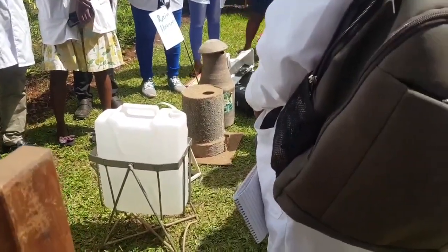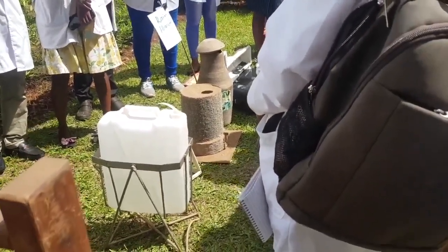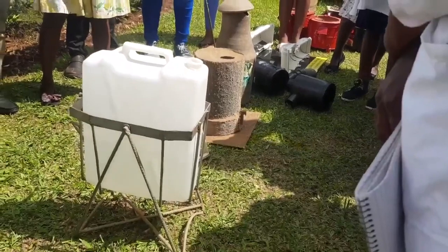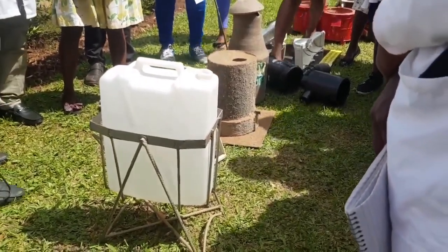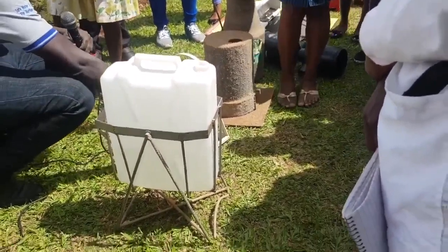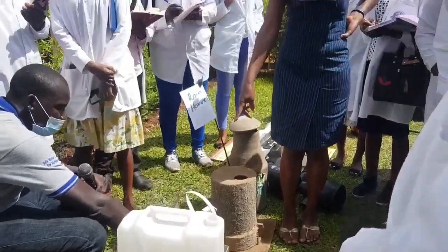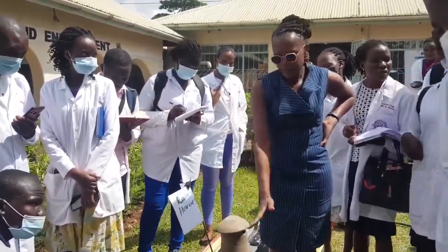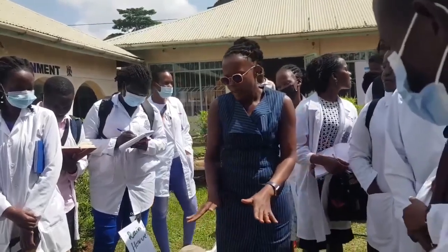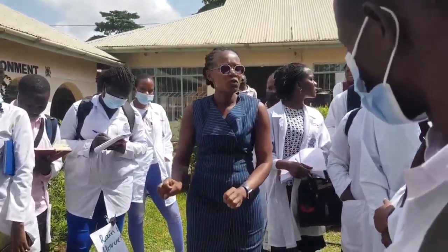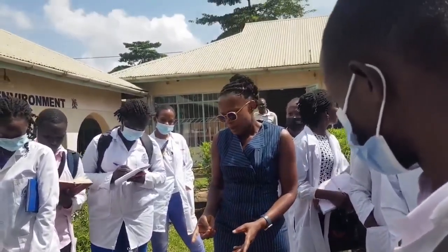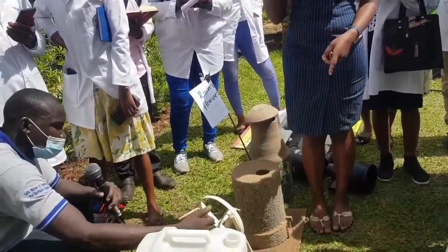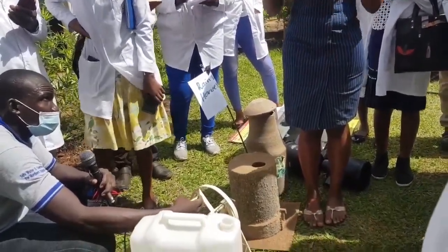You know, when we construct underground tanks, the challenge is getting water from there. So the EMAS tank has its own pump. It's called the EMAS pump. But the other tanks don't have pumps. So we either use electricity to pump water to an elevated tank, or you can do it manually. You can install a rope pump that you can use to pump and get water, the way they do at the borehole. The advantage is that you manage to control the water usage. As you rotate, they are easy to construct and easy to maintain. Though they have a rope that keeps on breaking, so we encourage it to be used at a small scale.